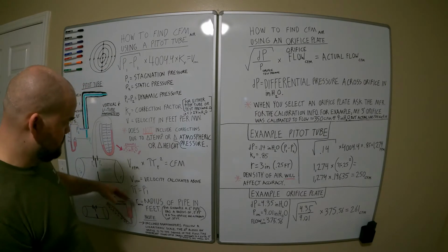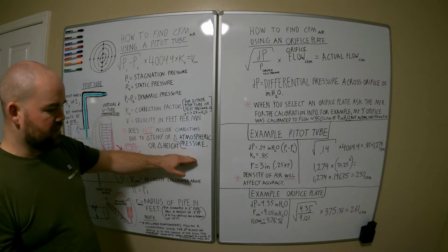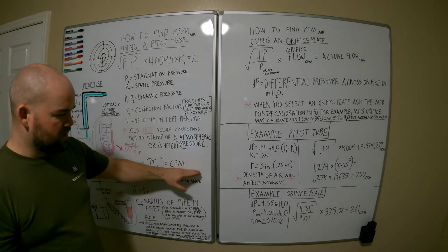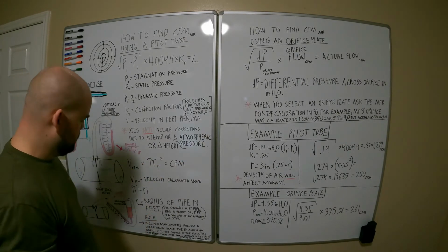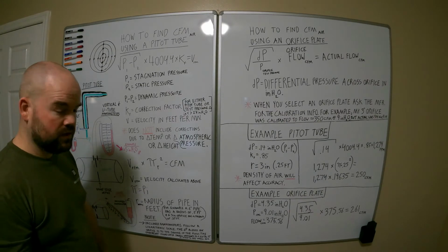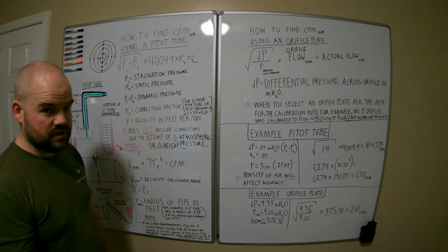So you may be flowing a cylinder head and you have 60% of flow at the 2.5 inch orifice scale, and then you may want to go up to a 3 inch scale as you get higher in your lift, and it's going to keep you in this 60 to 100% of the flow, okay? I recommend 60 to 80% of flow when I'm doing the tests.